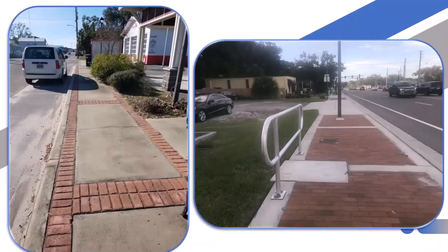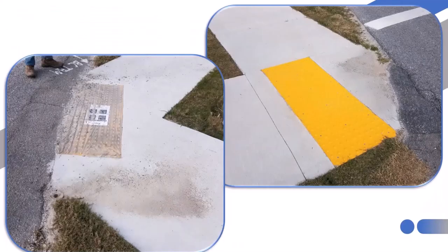For lessons learned, sidewalk brick pavers can be used. They're not prohibited on state projects, but let me say that the construction techniques and approach have to be pretty sharp in order for that walking surface to remain compliant over time. And you can use your imagination to see what I might be alluding to there. But if there become any changes in level or open gaps between the adjacent bricks, then that's going to become inaccessible as far as the ADA is concerned.